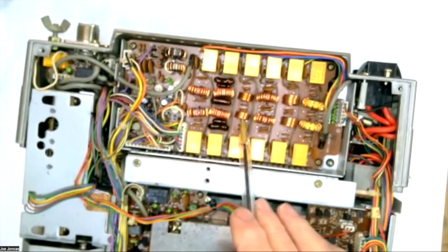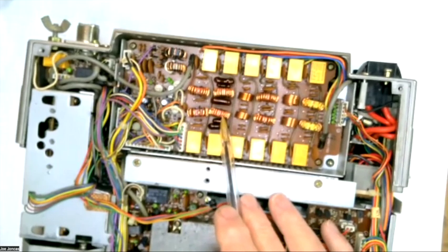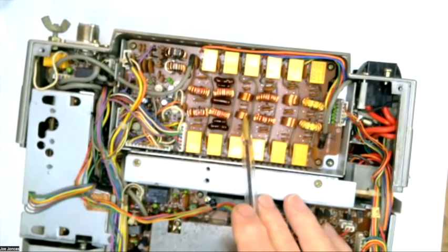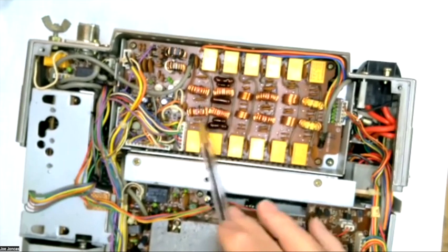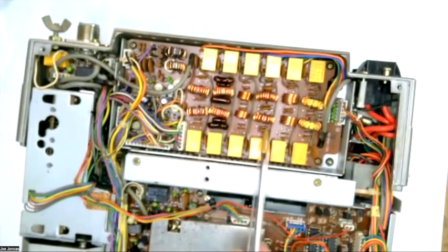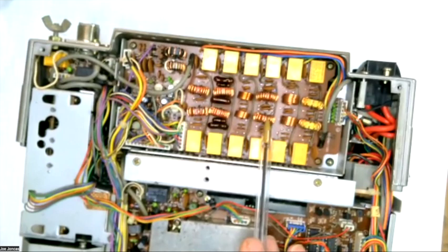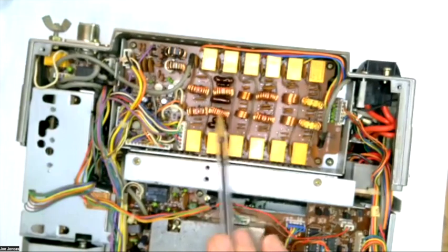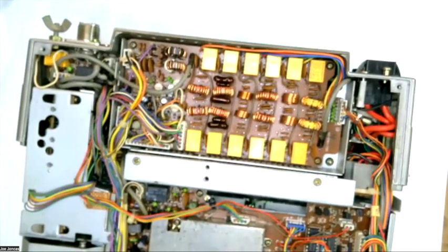This one is 28 megahertz. This one is either 80 meters or 160 meters. I'm not sure which. But see, this is the highest frequency and this is the lowest frequency, because we can tell by the number of turns on this coil. Remember I said that these can interfere with each other a little bit? I think that they've spaced them out like this to keep them from interfering with each other. I think they're using that as their method of isolation.